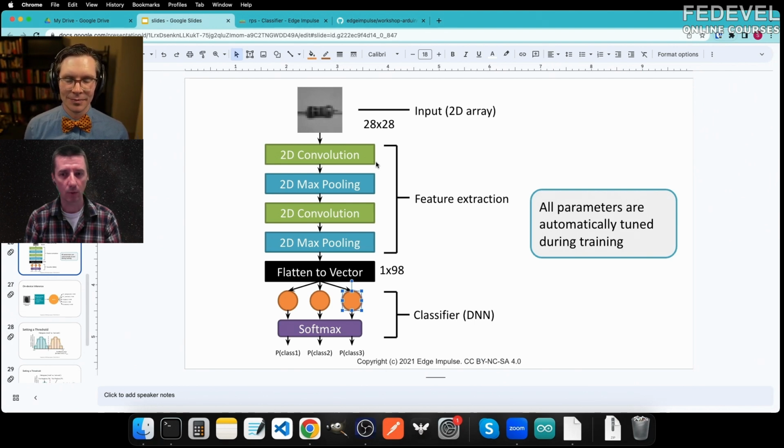And we need to have it inside of the model, because when we would like to use it, for example, on a microcontroller, we really don't want to do edge detection on the microcontroller. We would like to feed it with raw data and leave the model to find these edges and then decide what it is. I mean, it might be doing edge detection, right? Some of the convolutional filters that we set up might be edge detectors, and a lot of times they are. So you also have to run these filters on the microcontroller on the raw data.